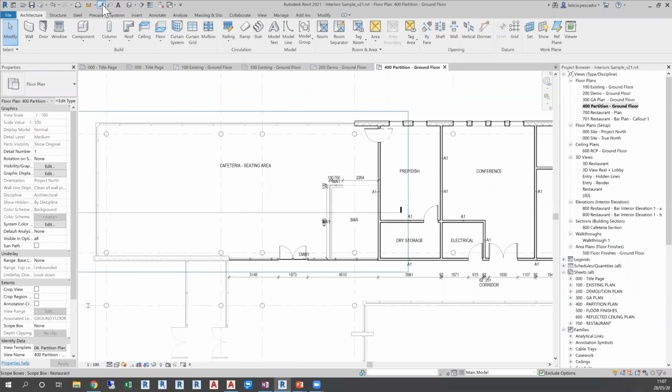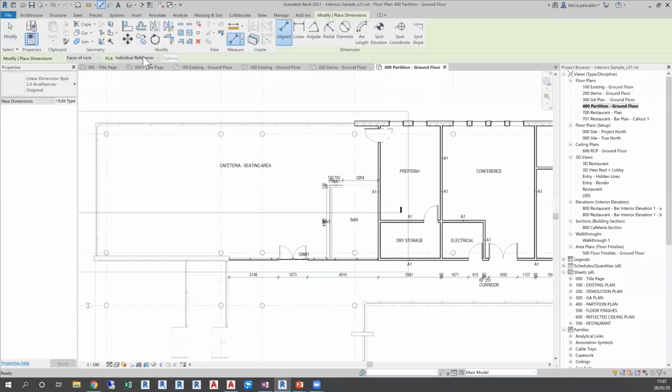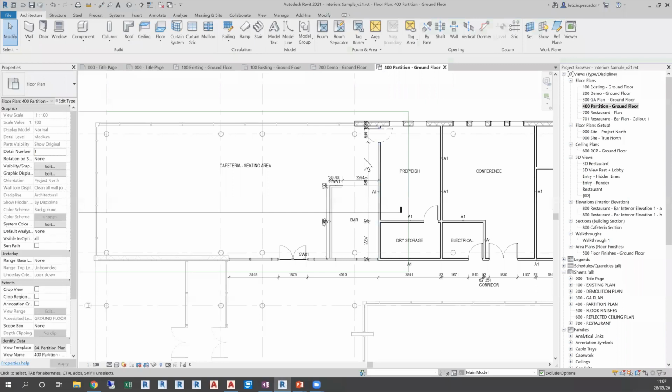Revit will have pretty much capabilities to dimension entire objects quite quickly. So here I just quickly placed a string of dimensions within the wall. So it will have capabilities to dimension the entire wall in one go. The phase two, it will change those behaviors within the color coding of those objects that are required to be removed.